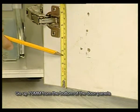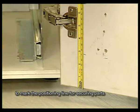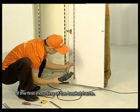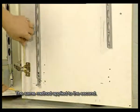Go up 70 mm from the bottom of the door panels to mark the positioning line for securing parts of the first mounting of the basket frame, and tighten the securing components of the first mounting of the basket frame. The same method is applied to the second.